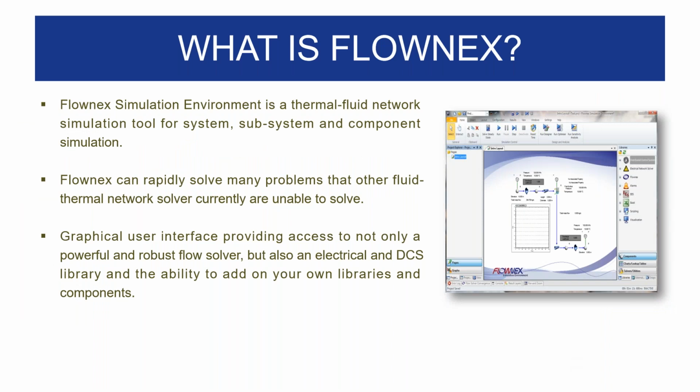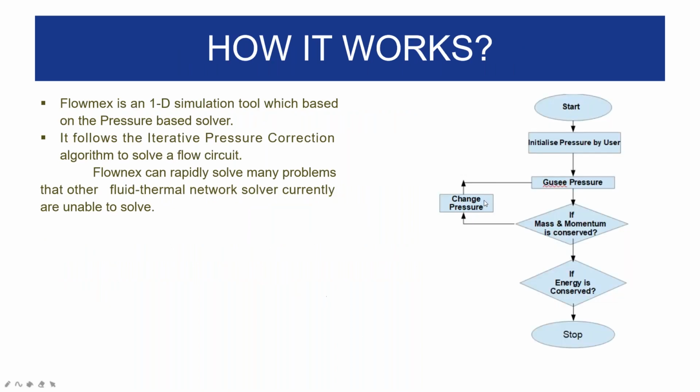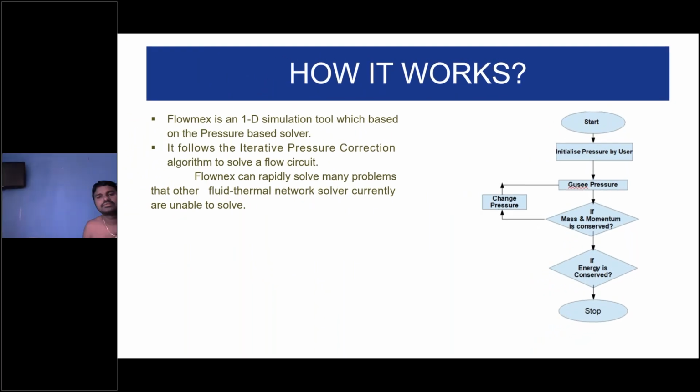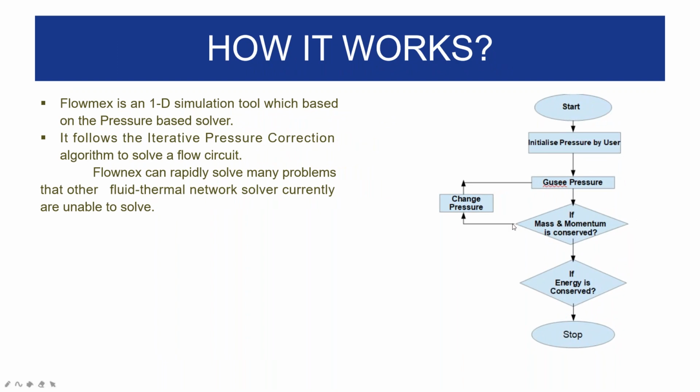Flownex is a one-dimensional CFD software, and it can solve different types of fluid-related problems. The solver Flownex uses is a pressure-based solver. In this solver, initially it will initialize a guess value, and from that guess value it continues to solve using Newton-Raphson's method and predicts the solution.